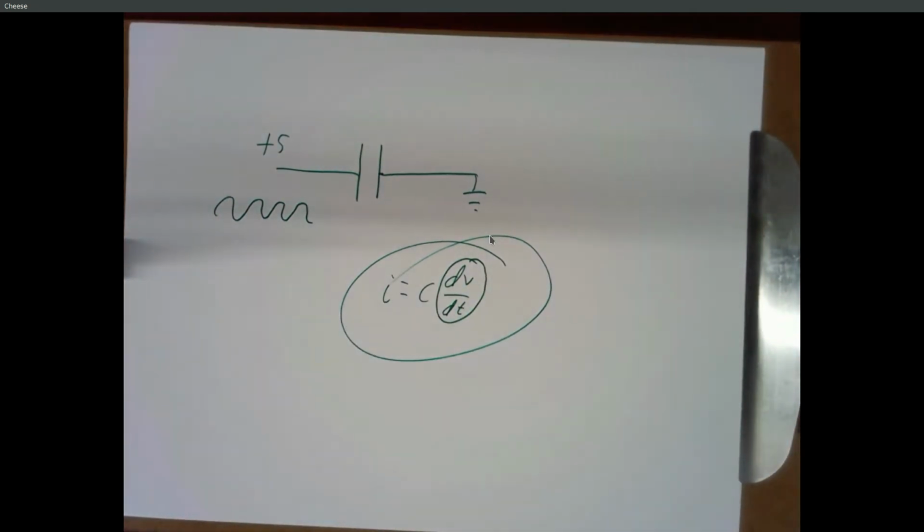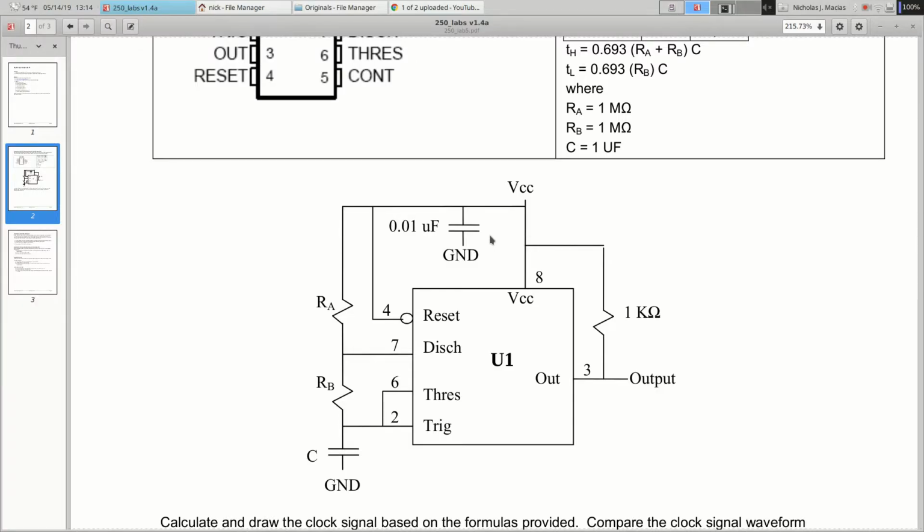Okay, why do we want this in our circuit? Because we want a nice smooth 5 volts for VCC. But that's not reality. Reality is the voltage is always wiggling around a little bit. Sometimes it wiggles around a lot. So those wiggles will basically get shorted to ground, while the nice clean 5 volts that we want will flow through into pin 8. So it's called a de-spiking capacitor, and its purpose is to clean up the power supply.